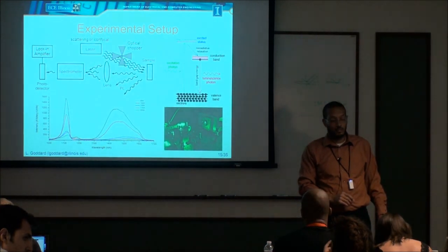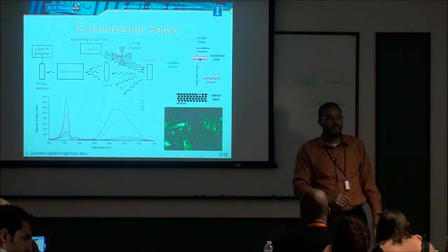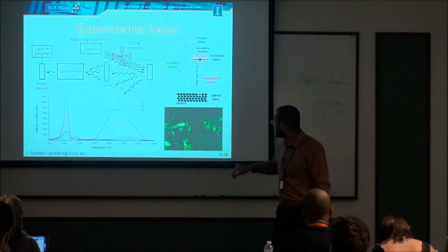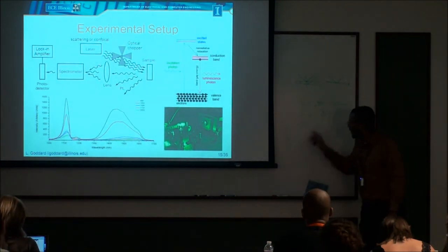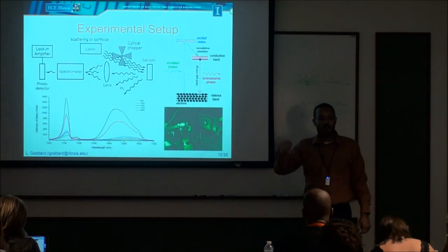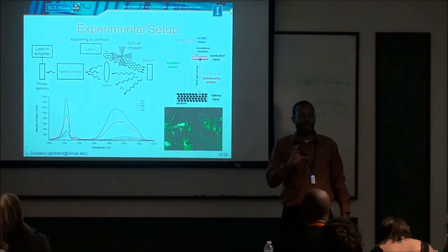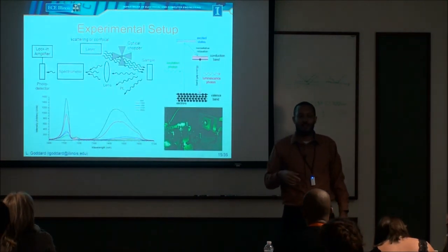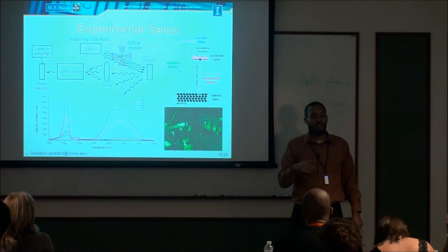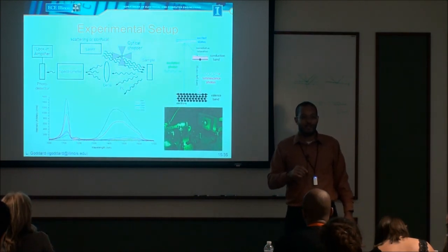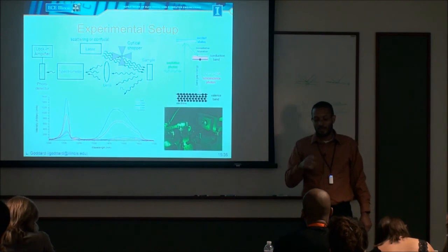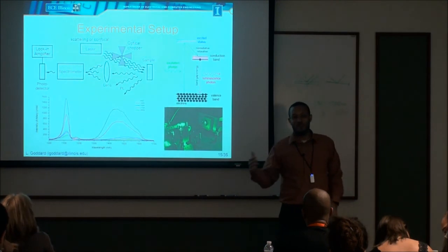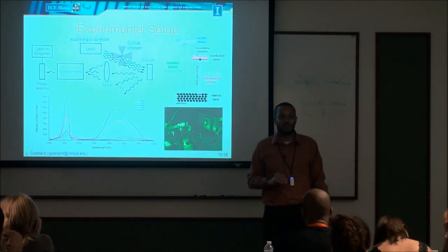These are mechanical. Oh, okay. One of the things I should mention is that when you chop at these high frequencies, typically the blade will have something like 60 grooves going around. So at 1 kilohertz, you'll be spinning at maybe 16 revolutions per second. So it's not that fast, but it's still pretty fast. You can feel a breeze coming off of it, so you have to compensate for that. You don't want it to blow your sample and cause mechanical motion of your sample.